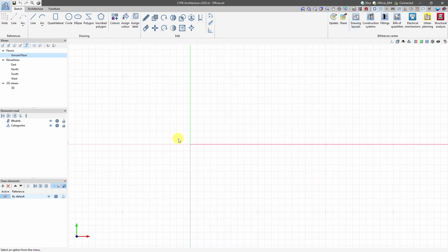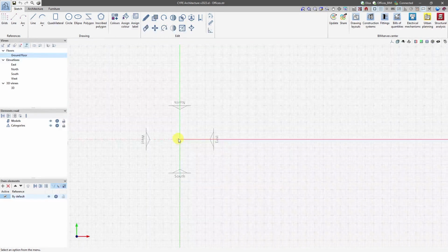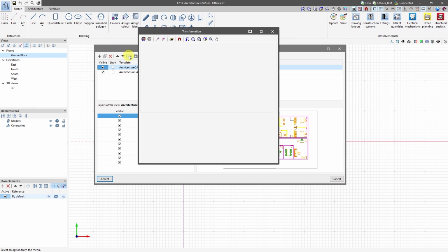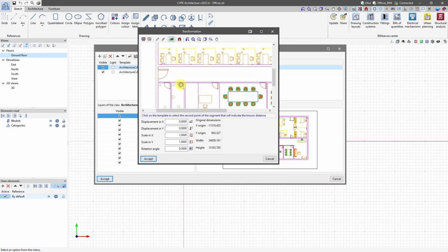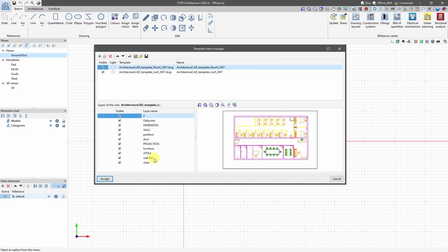When we zoom out, we find that the template is too big, so we click on the DXF DWG template option again. Now, we select this tool to calculate the scale from a given reference measurement of the project, such as the door, which measures 1 meter. We take the calculated value, which will be proportional in X and Y, to apply it to our job.